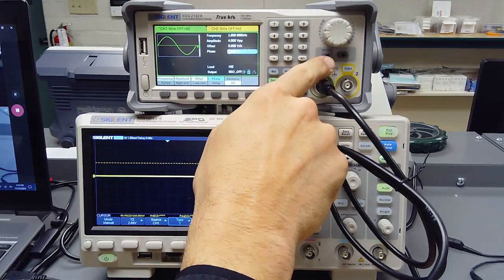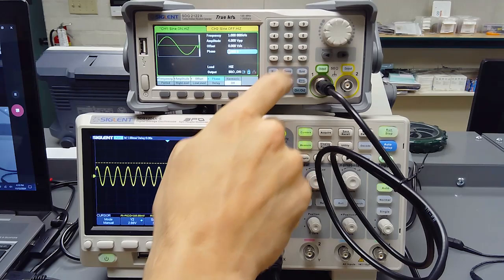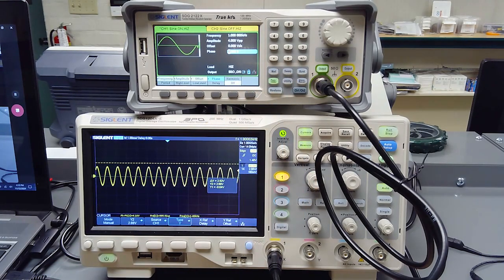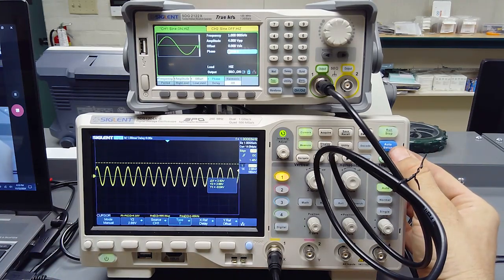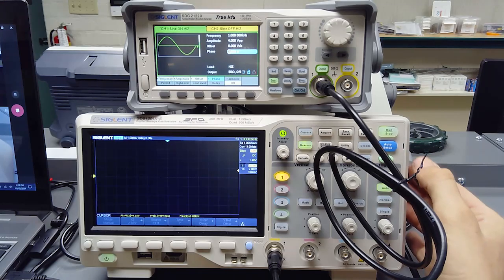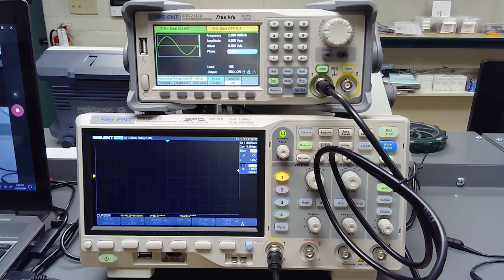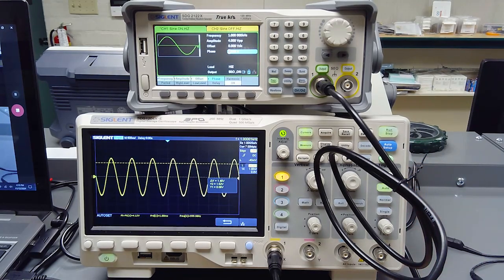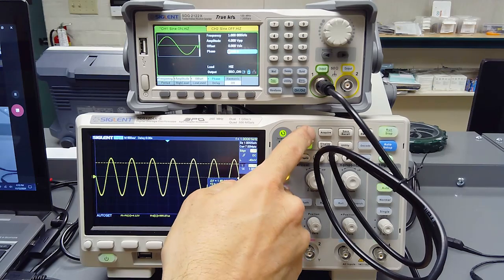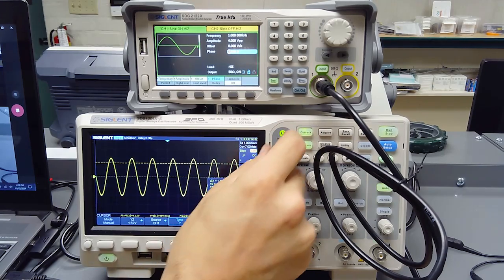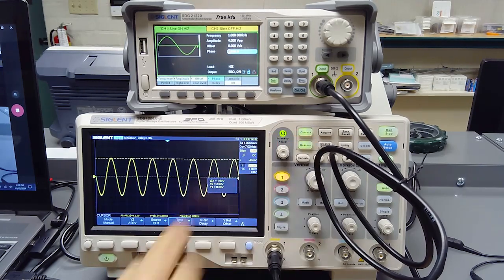We're going to press this button to turn the output on. Okay? And without having to do anything, I get the sine wave on the oscilloscope. If it doesn't show up, this should be something the scope should easily be able to figure out. Just hit the auto setup button, and it should be able to detect that wave and scale it appropriately so you can measure it. So if we go and verify some of these numbers here, we'll use the cursors. Let's start with Y. We'll put 1 at the top.